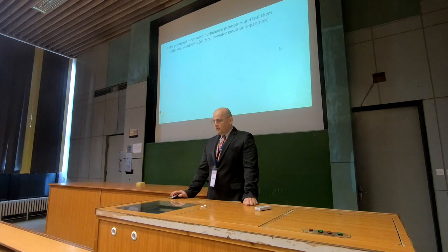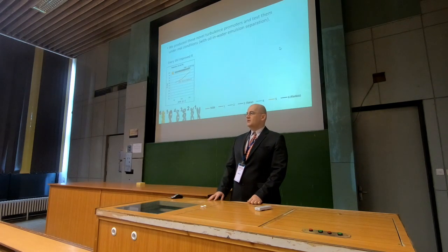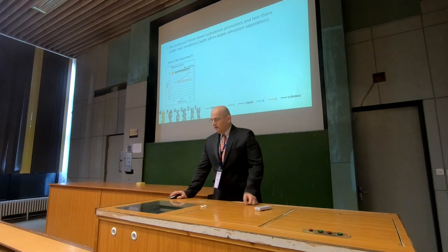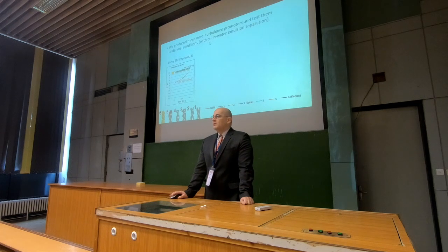And these 5 new turbulence promoters were produced and tested under real conditions. For example, I tested with whey and oil in water emulsion. Here I will show you the results of the oil in water emulsion separation. There is, as a function of flow rate, the retention. You can see that every static mixer improved the retention of the oil. With the red, there is the empty tube membrane without mixer.